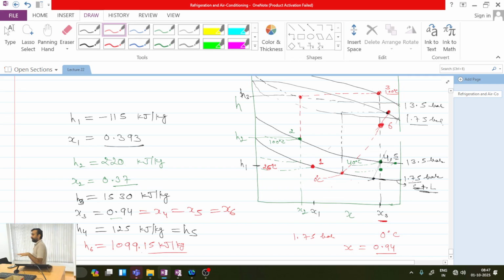This you have calculated graphically. This can also be calculated analytically. Shall I explain or leave it? You want to understand analytical formulation for this, or this is enough? Okay, so this is 0.6. Okay. Now this is an isotherm. It is crossing at saturated liquid point at this. So this will be my state 6F and this will be my state 6G. Is this part clear?